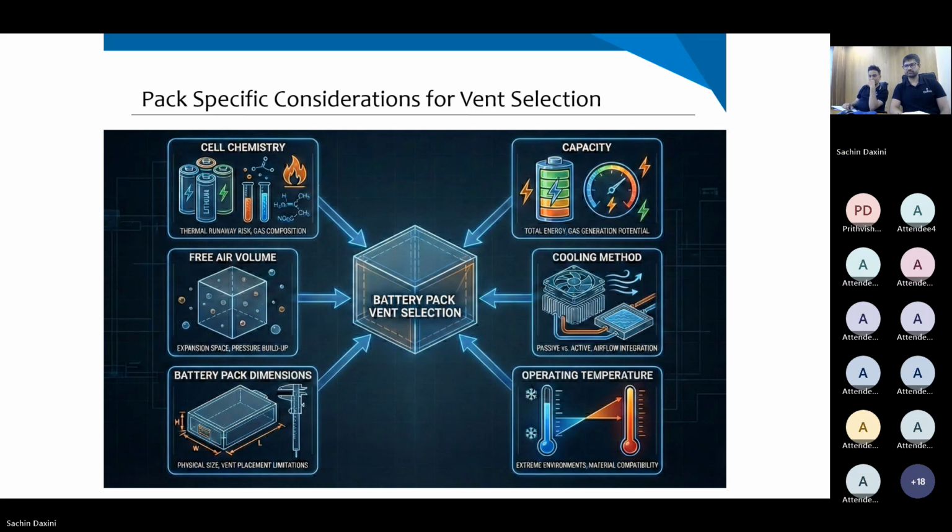Thank you. We have a couple of questions from Yash. Number one is, how are IP requirements met in case of threaded vents? Is it preferred to use Teflon tape on the threads? Usually it's not required, so our O-ring will take care of that. We will have a specific profile that your part needs to meet. There will be a chamfer profile or some kind of profile. So once you have torqued the screw to the value that we have shared in our datasheet, then you are protected from water ingress, water wading, depth immersion, whatever standards that we have committed. That part will meet those. So usually not required to put any Teflon tape. We will provide a detailed installation guideline also.